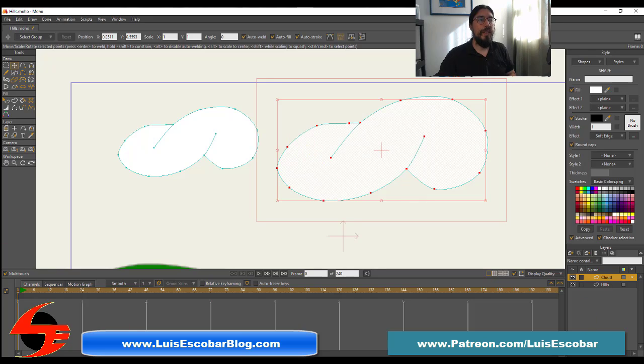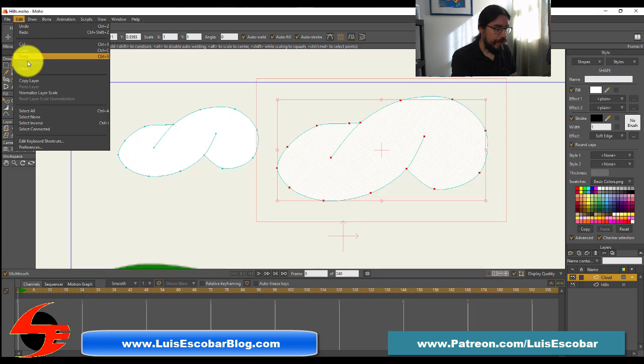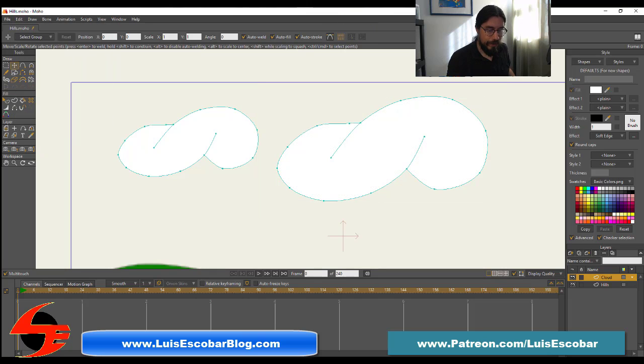Continue the transform points until you get the cloud to the position you like. Alrighty. To deselect all of the points, edit select none. Can I just press escape? Let me see what happens. Okay. If I have that and I press escape, that deselects everything too. I don't want to be going back to the file button.